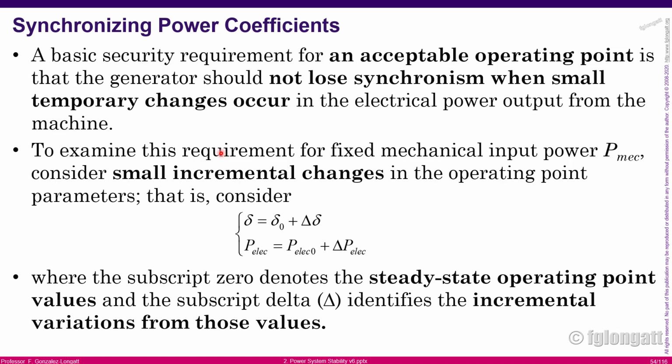What I will do now is use a very simple analysis to describe and define the synchronizing power coefficients. Let's say that we have a synchronous machine connected to the system, and I will make a very small change from the operating condition. I am concerned about the angle and the electrical power, because they are related through the power angle equation.